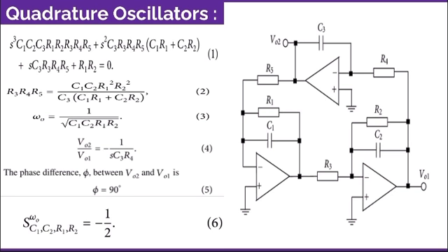This quadrature oscillator is used because the circuit provides two sinusoidal signals with a 90 degree phase difference. For example, in telecommunication for quadrature mixers and single sideband generators, or for measurement purposes in vector generators or selective voltmeters. In these cases, we use a quadrature oscillator. Therefore, these quadrature oscillators constitute an important unit in many communications and instrumentation systems.